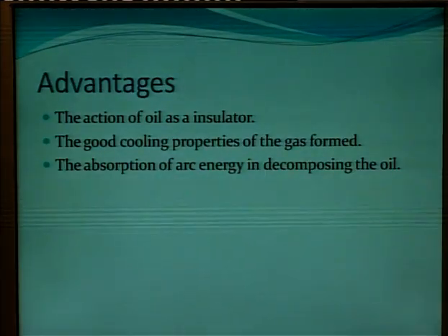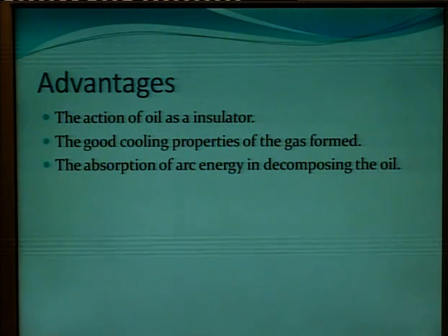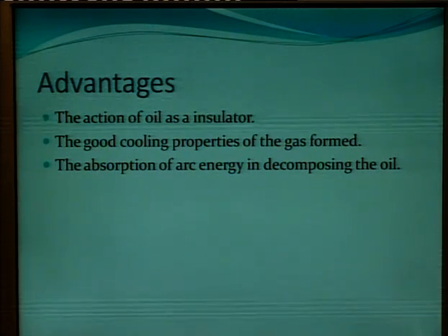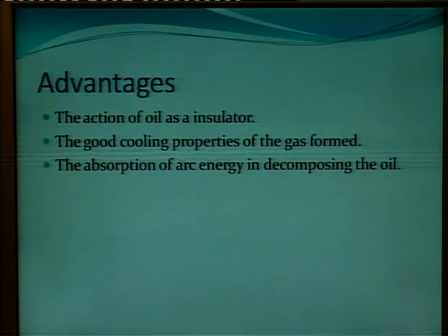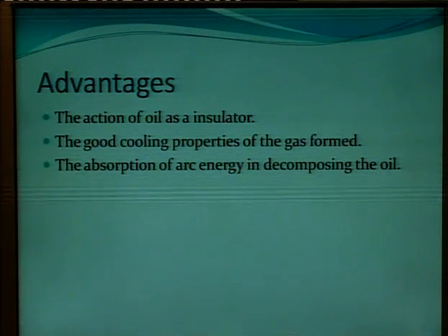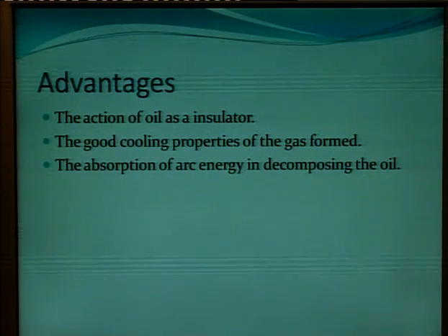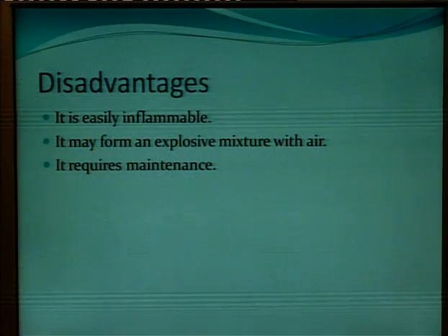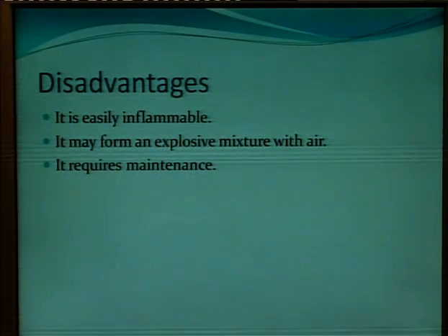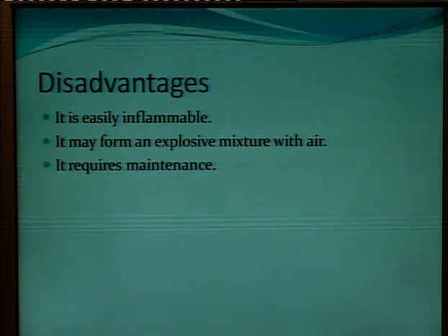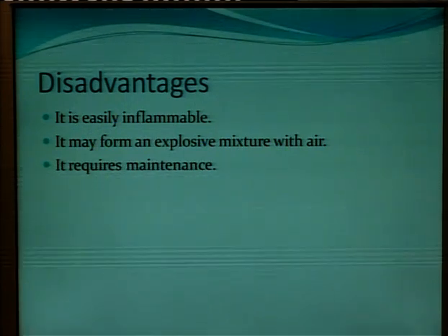Now the advantages: the oil acts as an insulator, the gas formed has good cooling properties, and there is absorption of the arc energy in decomposing the oil. Disadvantages: it is easily inflammable, it may form an explosive mixture with air, and it requires maintenance.